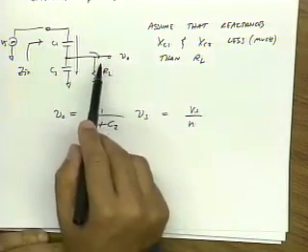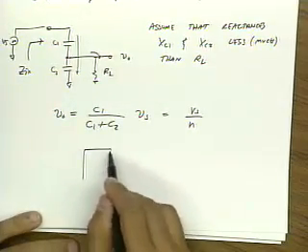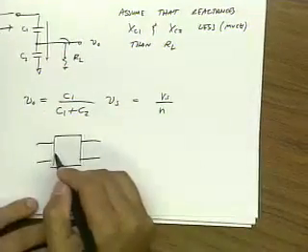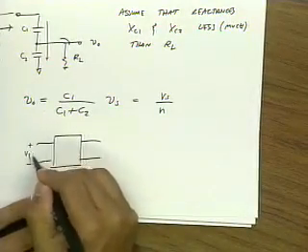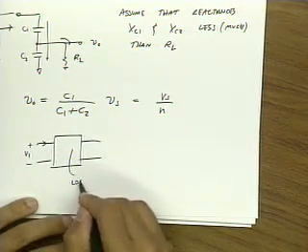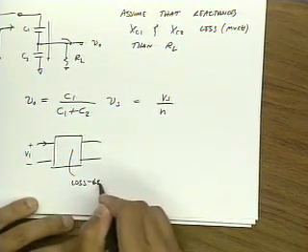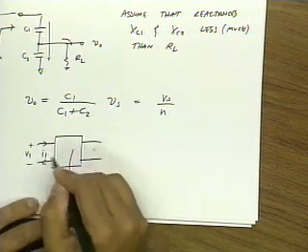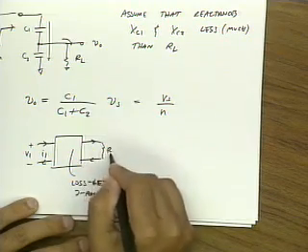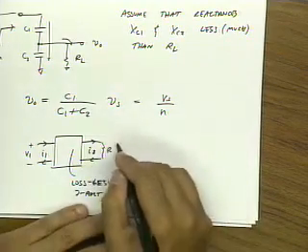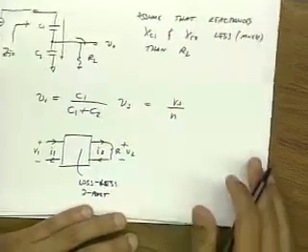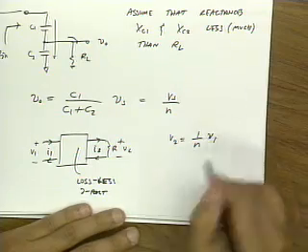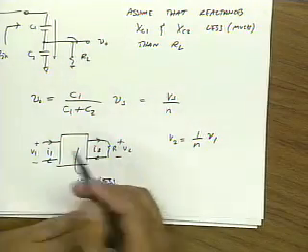Anytime I do a voltage transformation, I also do a current transformation. Let me just review that with you guys. Let's assume that I have a lossless two-port. And this is V1 and this is V2, I1, I2. And let me assume that V2 is 1 over N times V1, right? This could be a transformer, for instance.